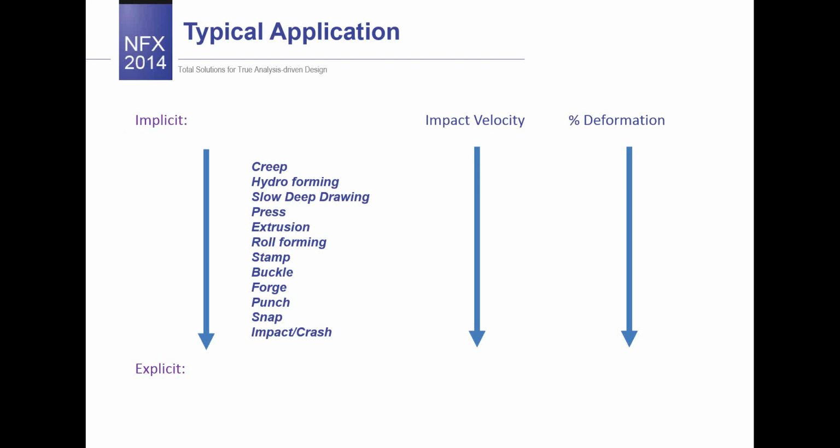Once again I will refer to the time steps, and generally the time step for implicit can be much larger. This makes implicit methods more attractive for transient events that occur over a long time period and are dominated by low frequency structural dynamics. Explicit solutions are better for short transient events where the effects of stress waves are important.